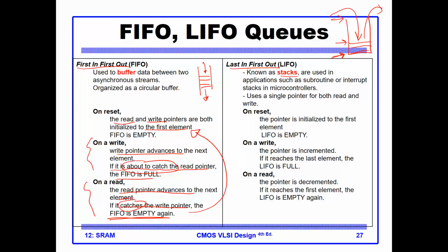So at reset, I initialize this top of the stack pointer to the first element, which is basically right here. Okay, and on the write, the pointer is incremented. So on the write, the pointer goes up like so to the limit of the stack on the top.